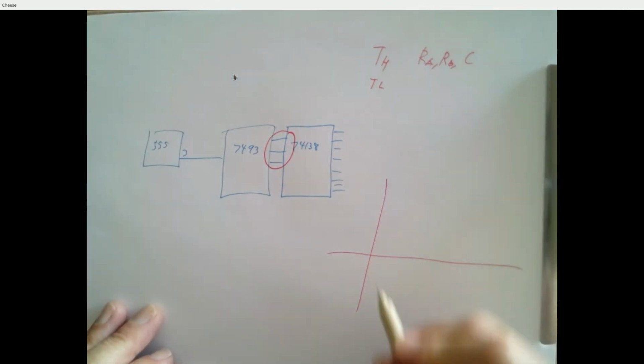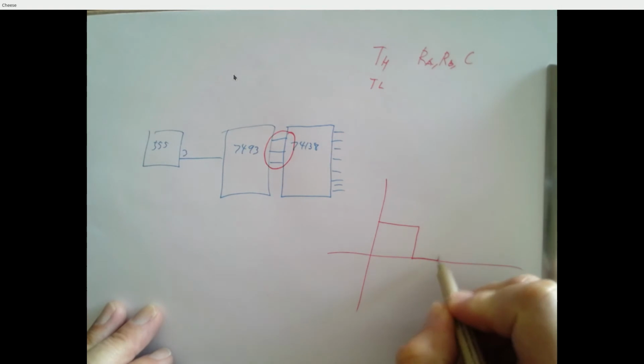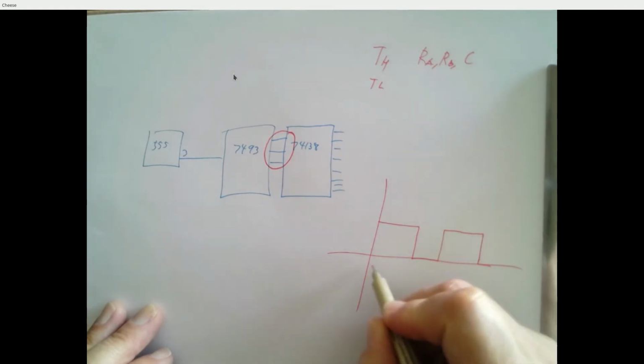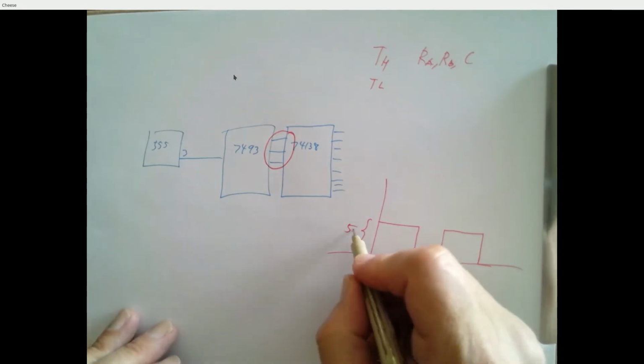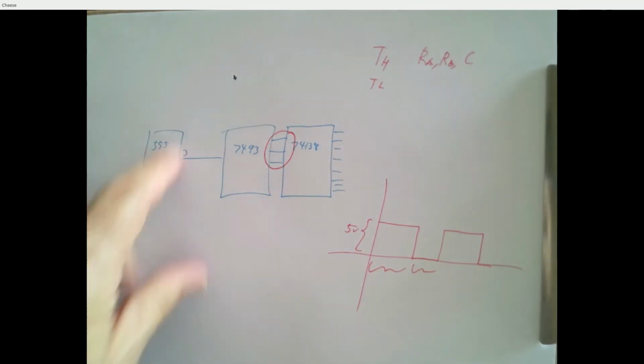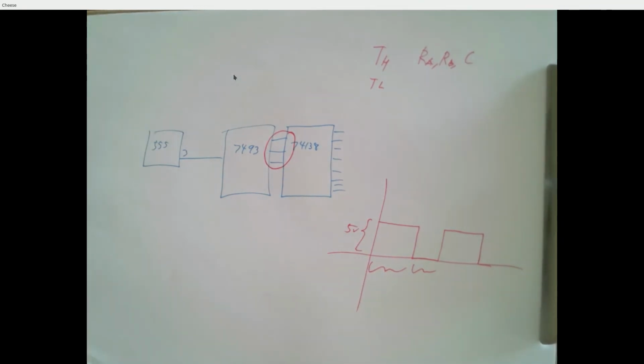Maybe a piece of graph paper, so high and low, and high and low, and how big is this, and how big is this, and you expect that to be 5 volts. And then look at the output on an oscilloscope, and see if you can figure out what the actual waveform looks like. And it's not gonna look exactly like yours, but it should be pretty close to your approximation. And then think about why might it be different from the theoretical.